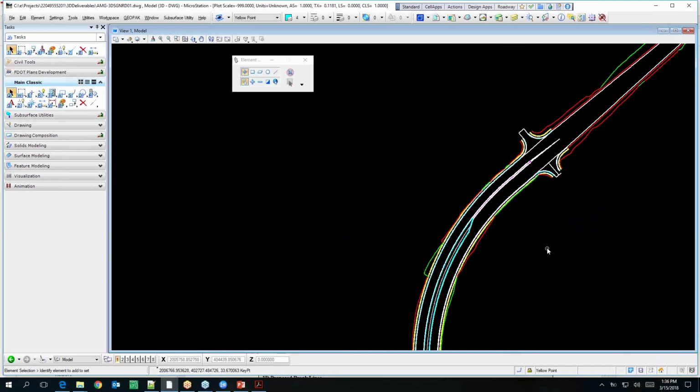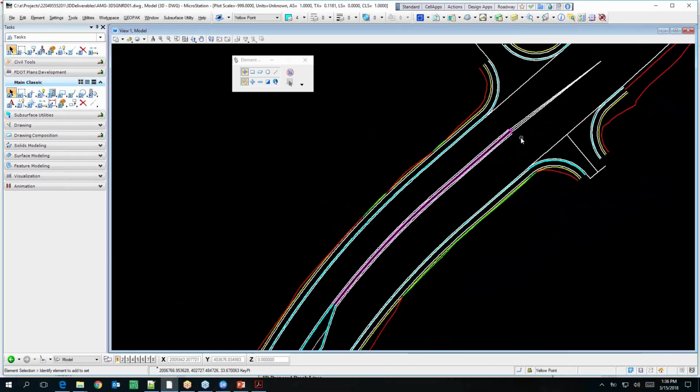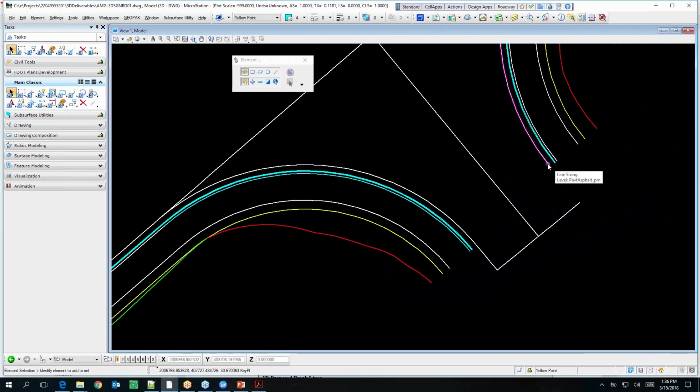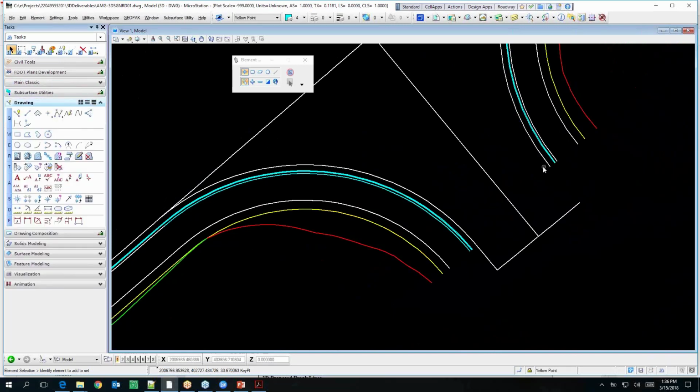Do you have a gap between your radius line? Yeah, you do. In the back of driveway line there, see that gap? Yeah. I wouldn't know how to create a triangle there. You can easily close it just by going to Alt and picking on a line, set that level of pavement, and then we can draw a line. You really should put this in your model, but if you're doing cleanup work, you could just do it that way. Yeah, the proper thing is to fix this in your model first, but since we're showing you how to fix this, if there's some minor stuff like this, you can fix it here. Because Trimble, any of the software that you load into, will throw errors.